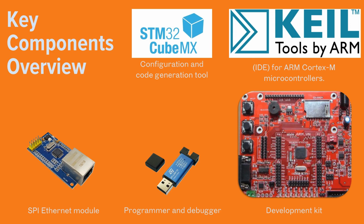On the hardware side, the setup includes a development board with the STM32F103 chip, which serves as the main BACnet device, an ST-Link V2 programmer debugger, used for flashing and debugging firmware, and a W5500 Ethernet module, providing the TCP/IP interface for BACnet IP communication.